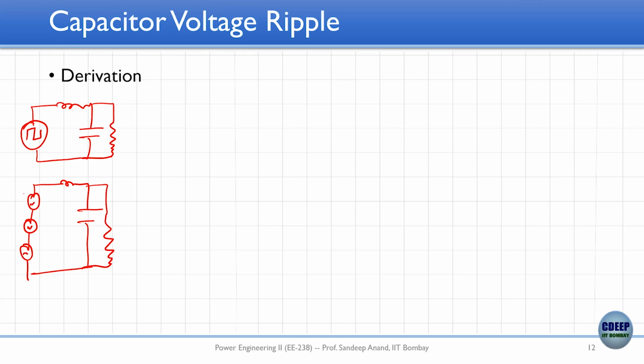In one case you will have only this one source of frequency Fs, in another case a source of frequency 2 Fs, in the third case a frequency of 3 Fs, and then you can solve for it, add those components, and you would get a triangle waveform essentially. So the frequency is the same because the circuit is linear. The shapes will change because there is inductor, capacitor, so different currents of different frequencies will flow. They may add up and start looking weird, square, triangle, some other shapes, whatever, right?